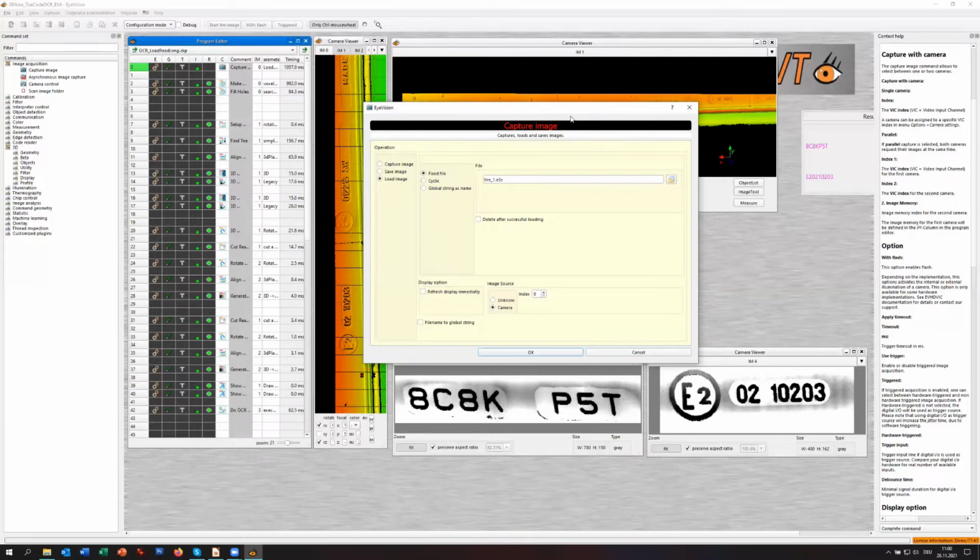That's why I said at the very beginning, for the EyeVision software, first of all, there is an image memory, and the capture tool either delivers to the image memory the information from the camera, or alternatively from a file. At the end, it's the same. And that's why you can test everything also without the camera, because you can load these image information directly from a file and operate on it as you have it from the camera.